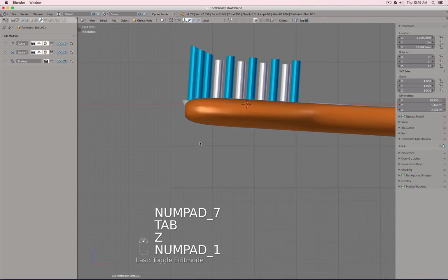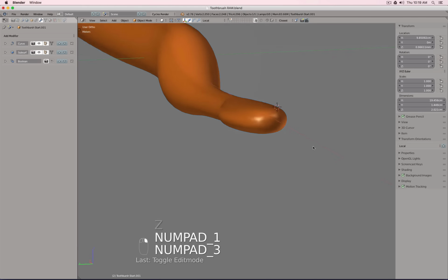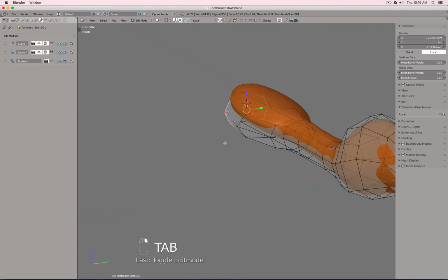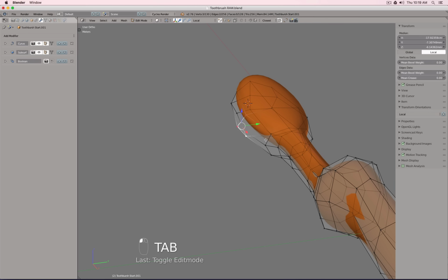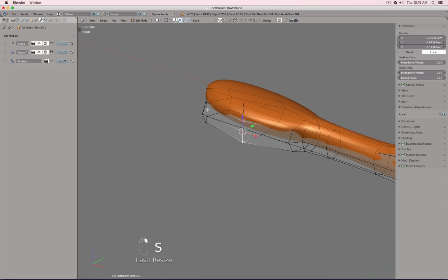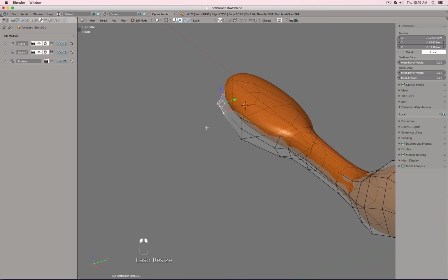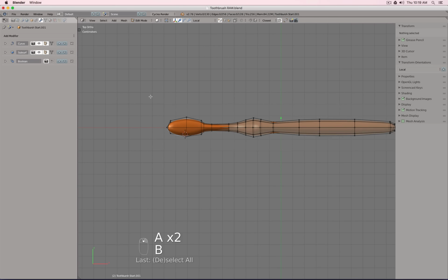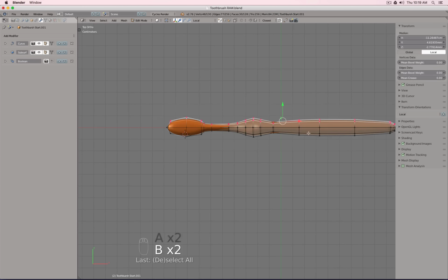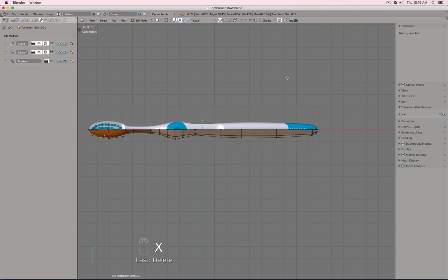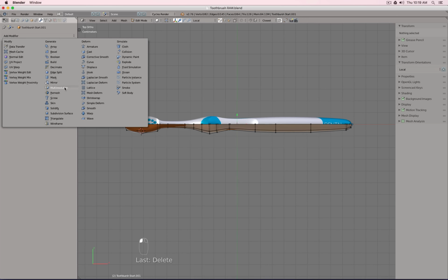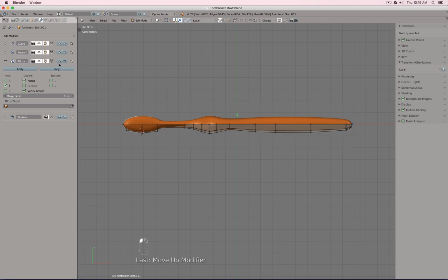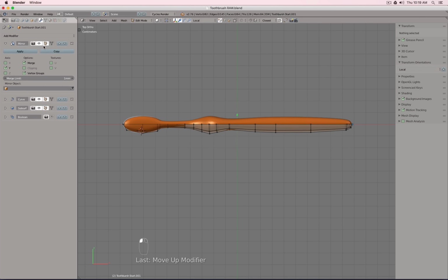Okay, so why did I do this? You see actually how I get this side flat, and there it's still round, but there it's flat. So I will do actually the same also there. SY and 0, SY and 0. And now I have two different sides. I don't want to do double work, so honestly I simply dump all this, and then I will come back with a mirror modifier along the y-axis and move this one to there.